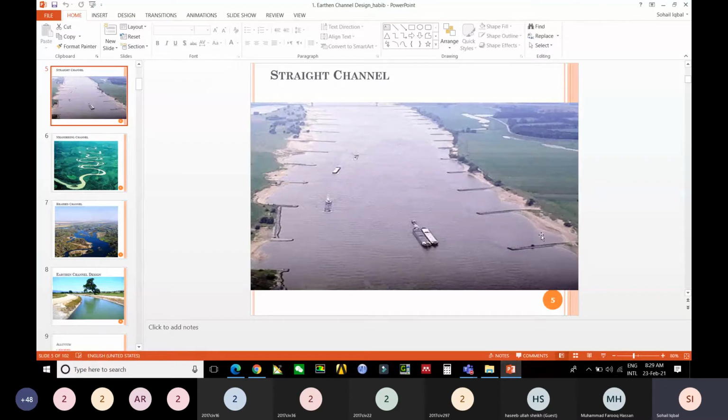यहाँ पे जो along the bank हो रही है, it's scouring, that particles move along, may move. It's not necessary that it always moves, because with the passage of time, यहाँ पे अगर downstream of spar dike देखें तो यहाँ पे velocity क्या हो जाती है, reduce हो जाती है upstream से downstream. When it moves from upstream to downstream, then the velocity will reduce, especially in this spar dike field.